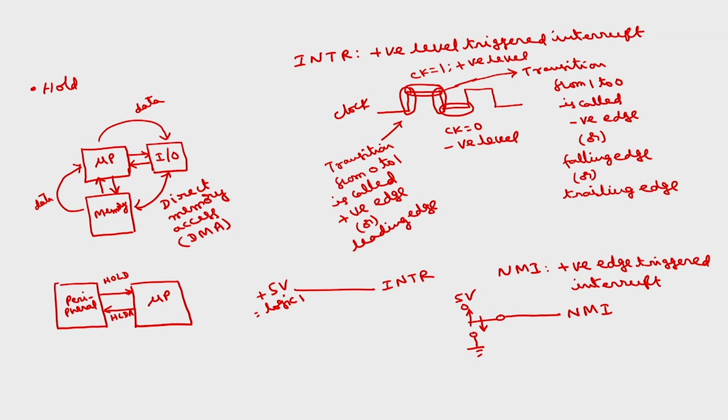Till now we have discussed all three types of the microprocessor operations. The first one is the microprocessor initiated operations such as memory read, memory write, IO read, IO write. Second one is internal data operations, like storing of the data, performing arithmetic logical operations, testing for the conditions, sequencing the execution of the instructions, and storing the data temporarily during the execution in a memory location called stack. Then there are some externally or peripherally initiated operations, which are reset, ready, interrupt and hold. And the corresponding hardware elements and the signals that are required for the 8086 we have discussed.